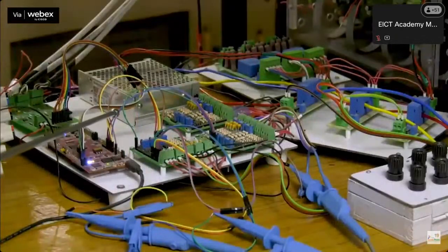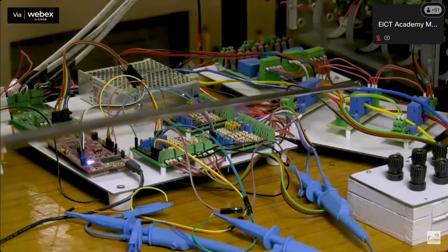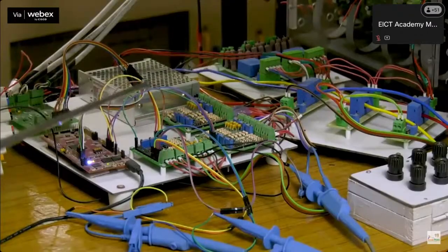The control system requires 3 voltage, 3 current and DC voltage signals as input and generates the required PWM pulses to control the grid-tied DC microgrid inverter. These input signals are given to the programmed control system in the DSP controller, which generates the required PWM pulses.